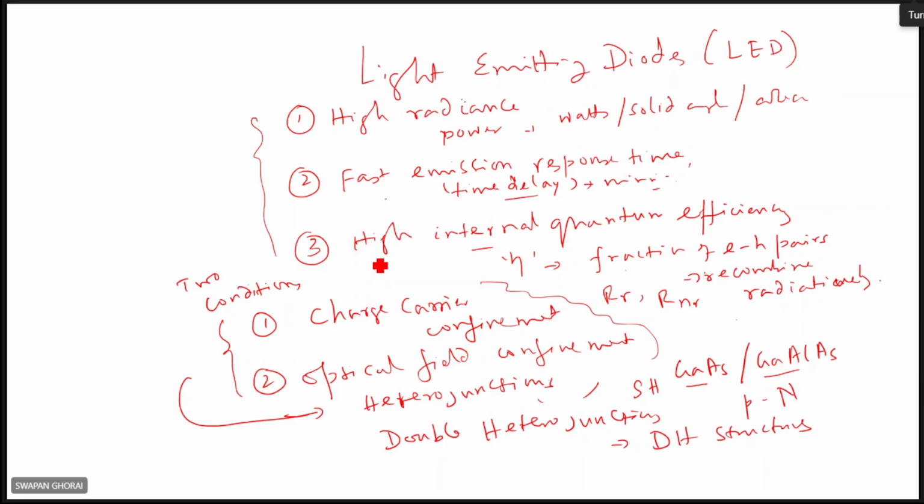And third, it must have high internal quantum efficiency. I told you about efficiency; it can be internal quantum efficiency or external quantum efficiency. Internal quantum efficiency is related to the fraction of electron hole pairs that recombine radiatively.